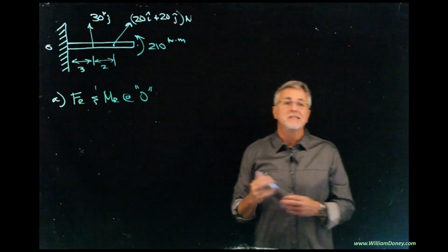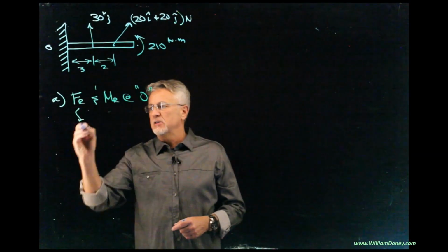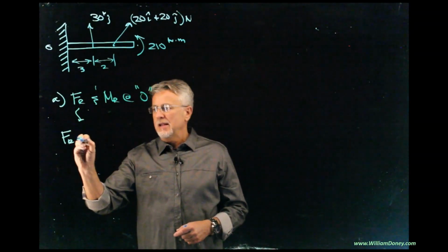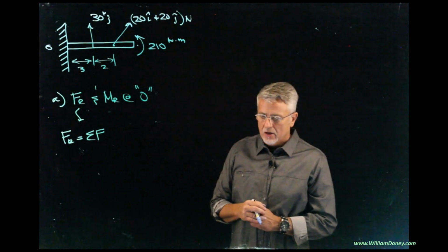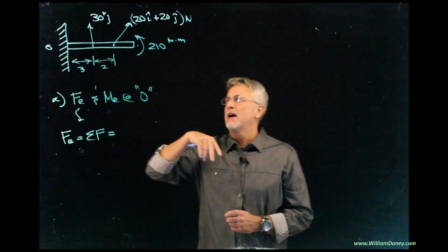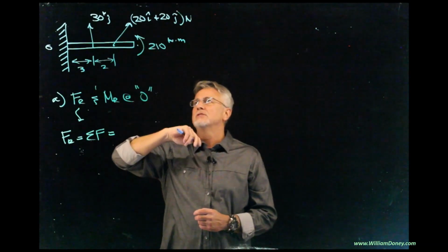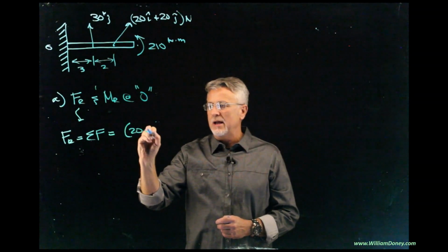This is 4.7, so we're just going to do what we've done before. Always, to get the resultant force in any problem, we sum forces. Okay, shouldn't be anything earth-shattering right there. If we go through and add that, I'm going to do this on the fly. We're going to stay in 2 dimensions there. We add the i's together, so we're going to get a 20i.